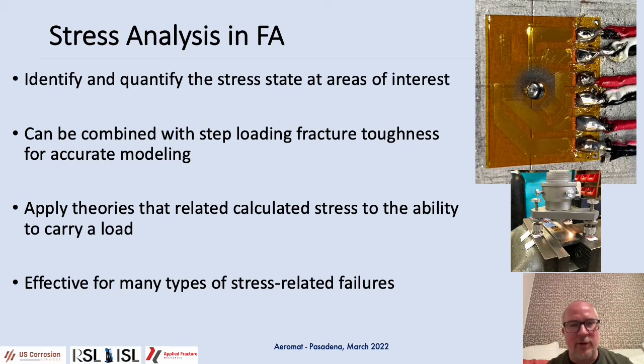And ultimately, then we can take that data and apply theories that are related to the calculated stress and that connect that with the ability of the material to actually carry a load. So this process can be used in a variety of stress-related failures. And one other thing I'll note is that the hole size determines how deep the measurement can be. So these strain gauges can come in very small and much larger sizes, and you can get to a fairly significant depth, or you can do it in a very small location, but with a limited depth.